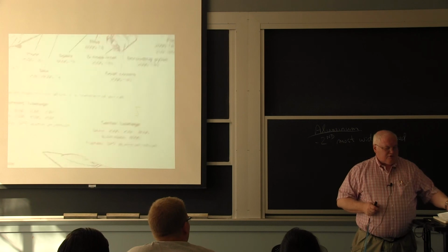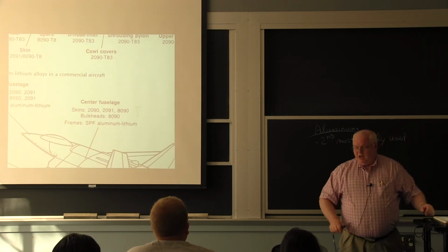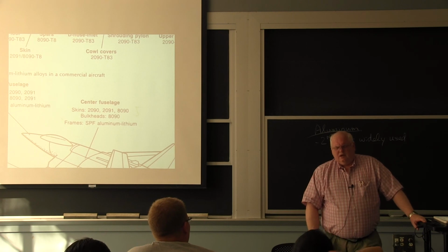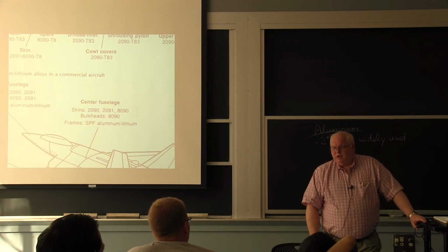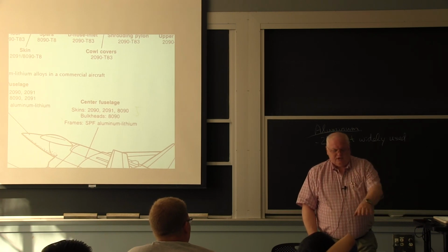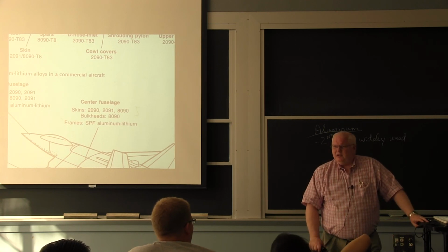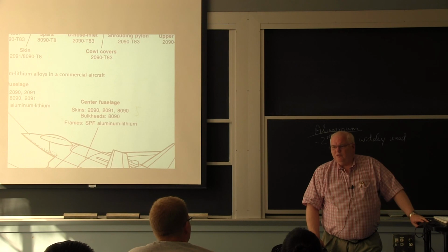No, because of corrosion resistance, stress corrosion cracking. And they've come up with 7079, which sort of started to replace 7075. If I started looking through, there's another one, 7175, I think it is. I can't remember the designations. But if you were circa 1960, 7075 and 2024 were the two workhorse alloys.